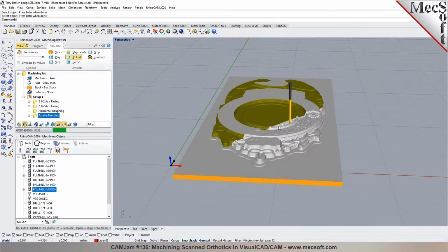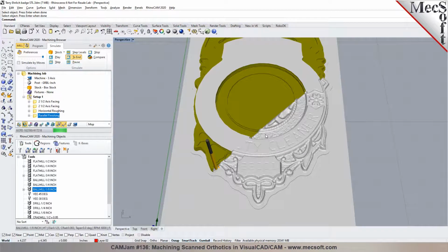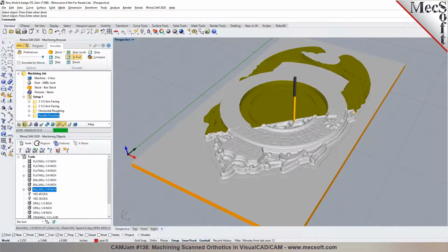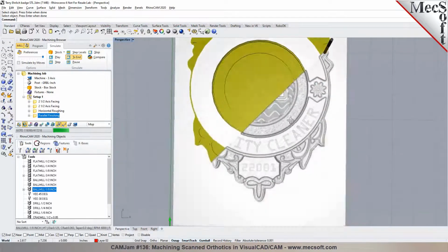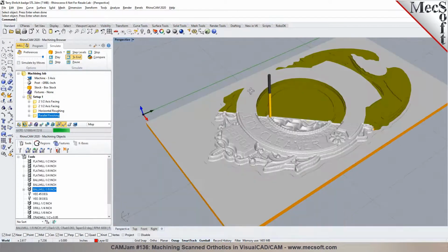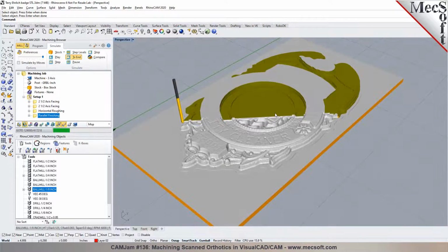And as you can see, it's running through it right now here. Any questions while it's being simulated right now? Not really. Now, what type of toolpaths have you been generating with your current program? It's only pretty much a raster file. So it's a Z level for roughing, and then, because I'm doing wood most of the time, I'll normally choose an angle across the grain of the wood, so I'm always cutting cross grain. Okay.